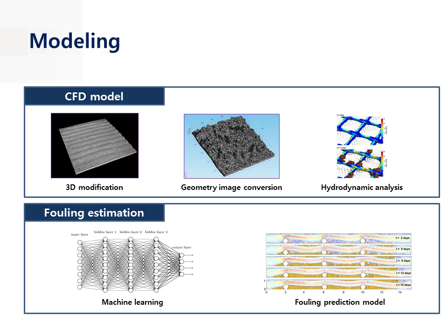To develop the fouling prediction model, we are going to consider a machine learning method with a variety of experimental results as input data. In this model, the fouling index, which is the dominant factor of membrane fouling, would be used as a key parameter to predict the fouling phenomena during the operation.